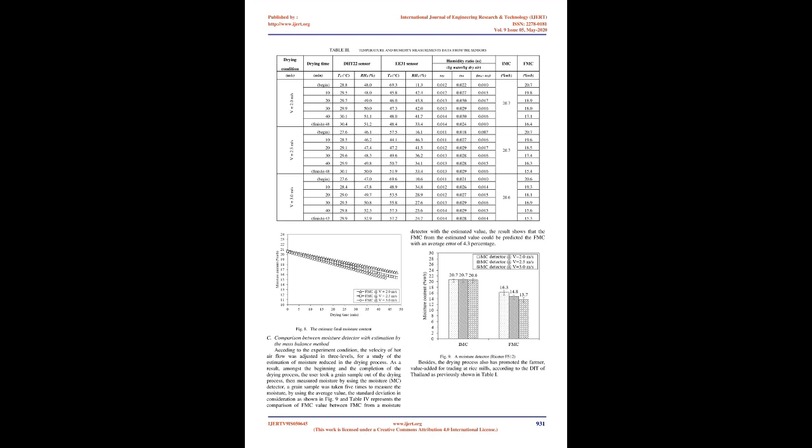The humidity ratio identifies the ratio between the amount of moisture, or water vapor, in the air and the amount of moisture the air can hold. The humidity ratio is shown in the humidity ratio column in Table 3. Secondly, calculate the mass flow rate of the air at inlet and outlet, as explained in Equation 2. Then multiply these values by the humidity ratio as in Equation 5, to estimate the mass of water removed from the paddy, as in Equation 1.